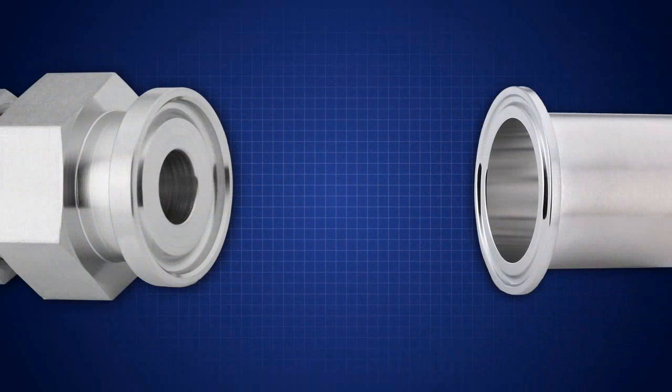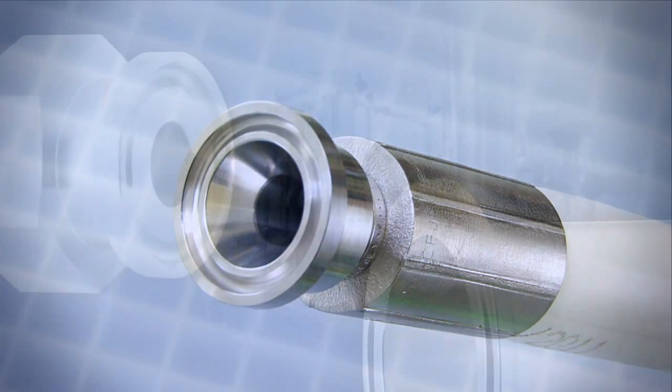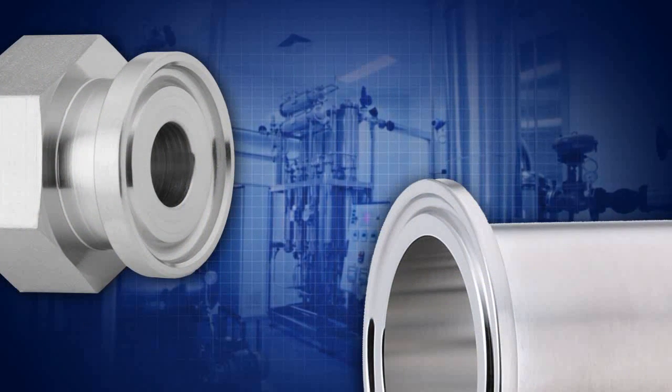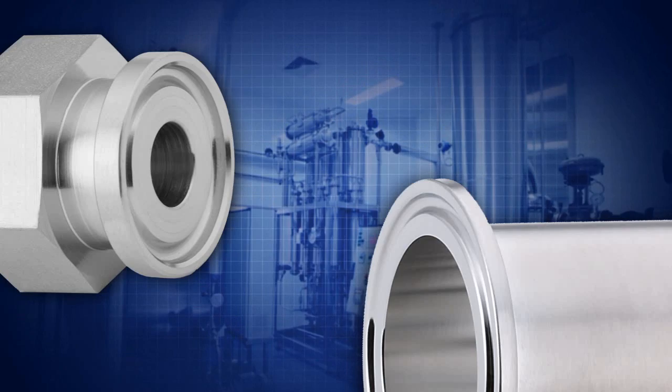After identifying the flange dimensions, it is determined that the appropriate end connections are a 1/2 inch sanitary quick clamp on one end and a 3/4 inch sanitary quick clamp on the other end. Note that it is important to identify the inside and outside flange dimensions to determine the size and standard of the hose end connection to prevent system contamination.